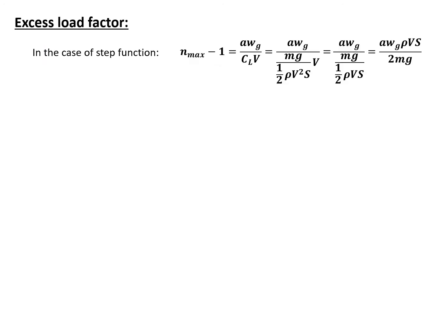Okay, and we've already derived the maximum excess G loading from the step function. If we use the current realistic function, the 1 minus cosine profile, we can express the maximum G loading very similarly to the one above using the step function, but we have an additional kg on the right-hand side. What is kg, you may wonder?